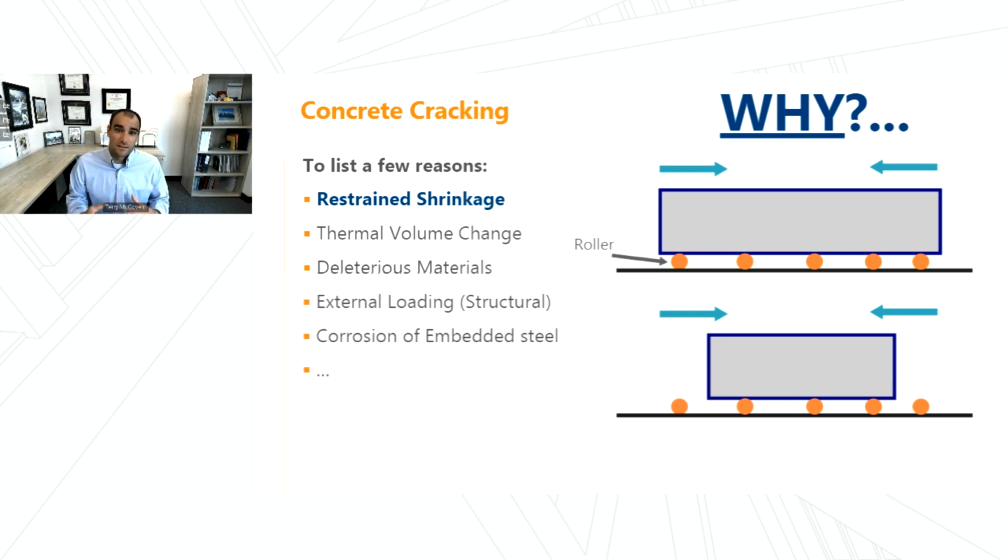The third is that concrete's a sponge, and so it has some excess moisture in it. And that excess moisture that's not needed for the curing of the concrete is going to dry out over time. And as it dries out, the concrete's going to shrink down a little bit, right? So we've got the three main aspects, the drying, the thermal, and the chemical reaction or autogenous shrinkage that's resulting in that reduction.